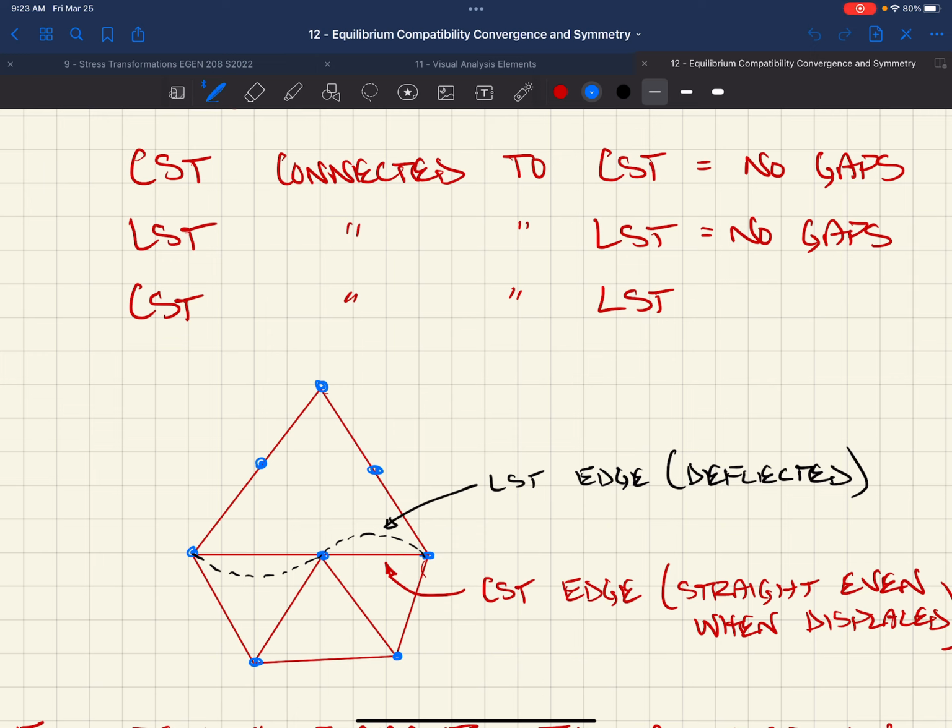And if you did decide that you wanted to switch elements, maybe you had some weird stuff going on. When I modeled the spreader bar in that class, I modeled how shackles were sitting inside the holes on the spreader bar. So you have what we would call contact elements. They can only press against another element. But I didn't use those contact elements everywhere, so I had to make a transition between elements. I wanted an element that could make that little touching between the spreader bar,